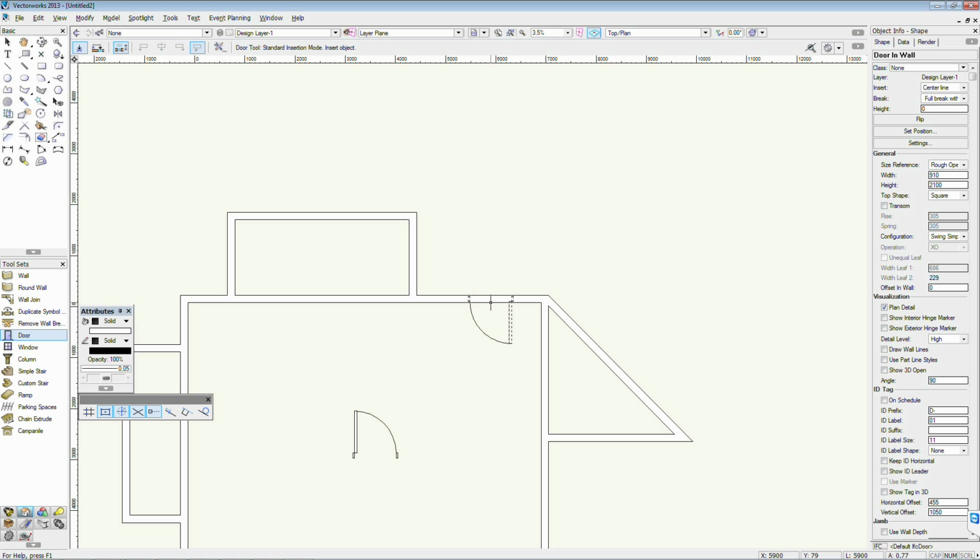So an important thing about placement, once you've chosen your location for your door, you get 4 different options, and it works in a quadrant system. So if you think about me heading currently northeast out here, I've got one orientation. If I head to the next quadrant, which is 90 degrees around from that, I get the second orientation, the third orientation down here in this corner, and the fourth orientation up here. So you can just switch between your orientations by crossing those center points. And then once you're happy, just second click to finalize.